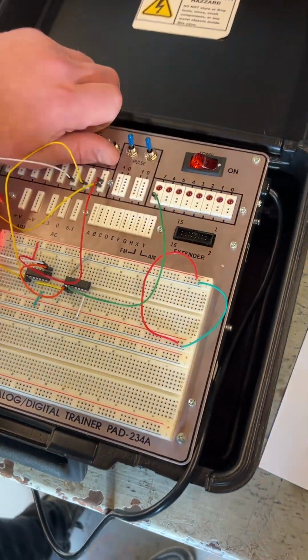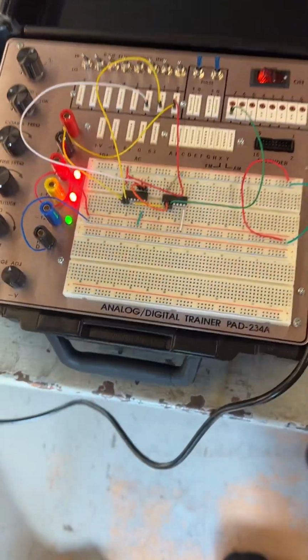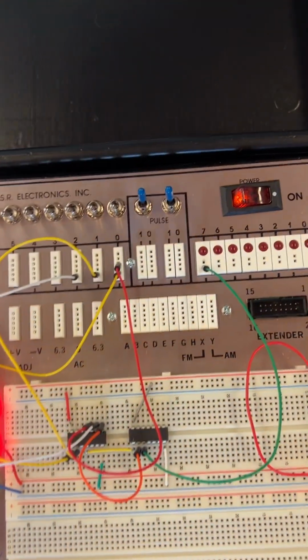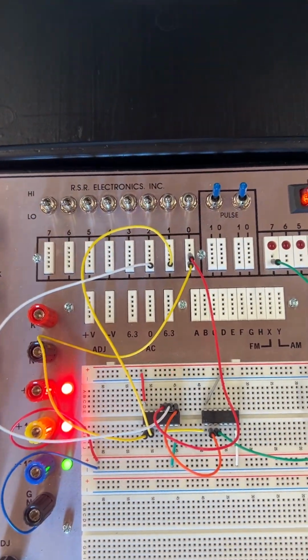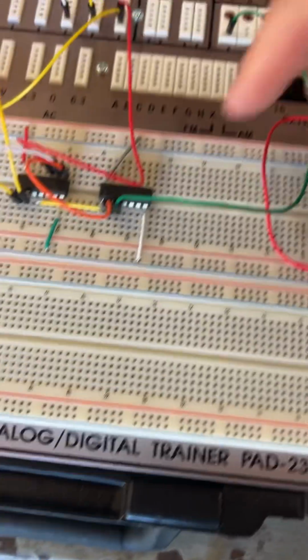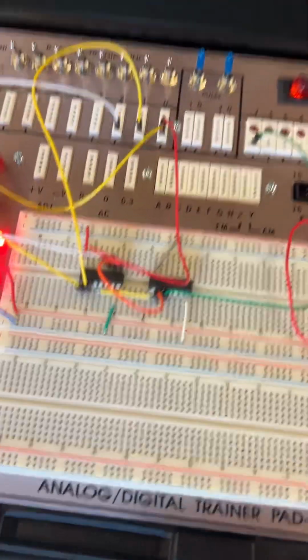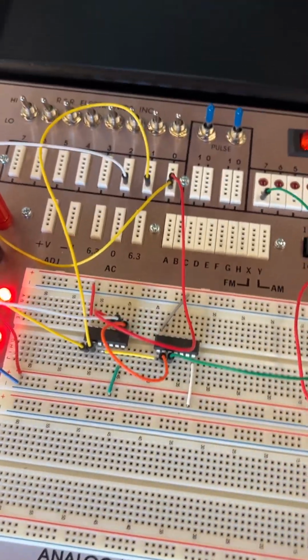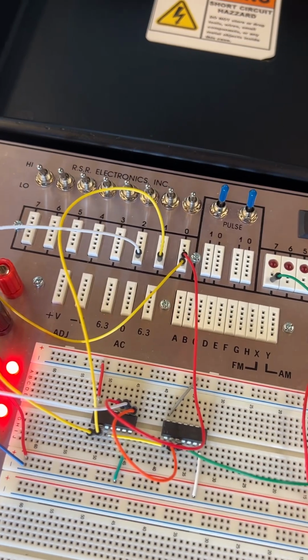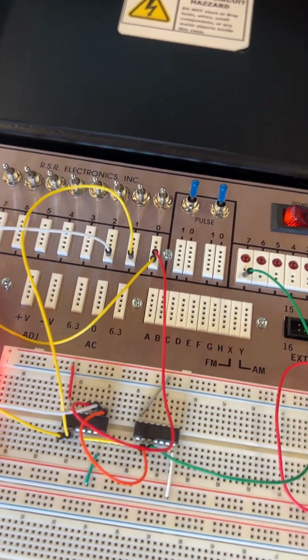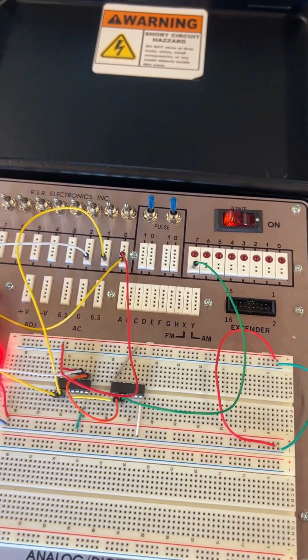For troubleshooting, we had an issue. We came in where the LED was on and no switches were on. We noticed the OR gate here was elevated a little bit, and the chip actually was bent, the one for the power here. Once we fixed that, we had a working circuit again.